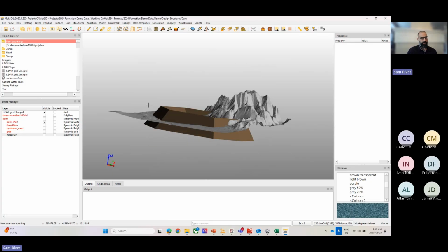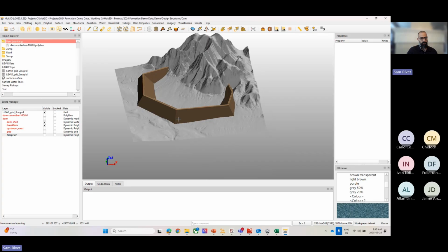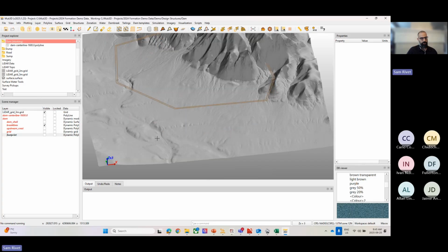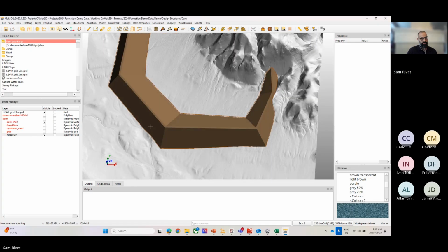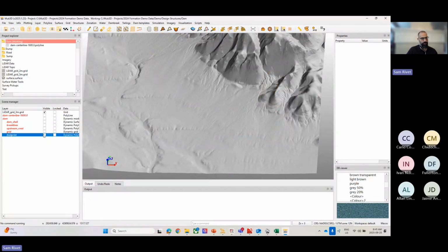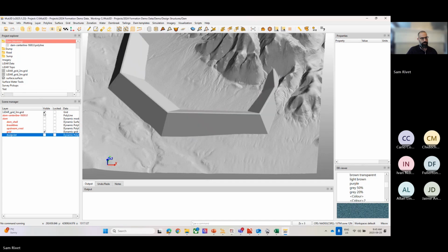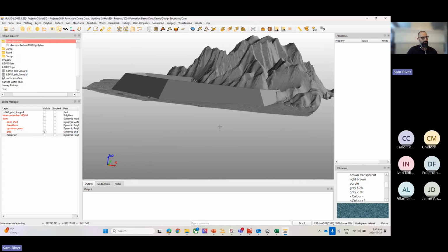And the dam shell. The break lines associated with that dam shell: crest, toe, the upstream crest, the footprint of where that dam shell intersected topography, and probably most importantly, a merge grid. So it took that structure, merged it into the surface, and clipped it.